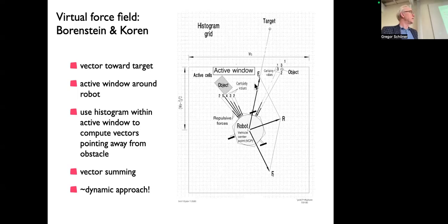So it's not quite track dynamics. We would say track dynamics if you were to erect dynamics of the heading direction, and then you go for the local attractor. They did it algorithmically. That is, they chose the direction where these vectors are small and then took the direction that's closest to the target. It's sort of like finding the right attractor in a way. And you can imagine that can jump around. This is not perfect, but it's also low computational cost.